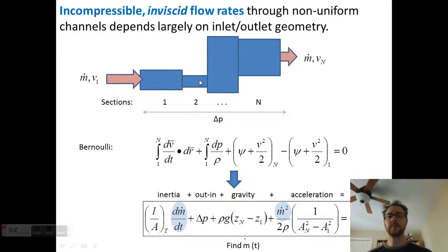It'll go through that pipe, and then it'll squeeze into the reactor and travel through the assemblies, where it heats up again, receiving energy from the fission reactions, causing the fuel elements to heat up and then transfer that energy to the fluid. And then it may come up to the top of the reactor core and enter a large exit plenum before going into another large pipe that leads it to the steam generator, and it'll go around in this circle. We'll have a number of different area changes and different pressure effects.